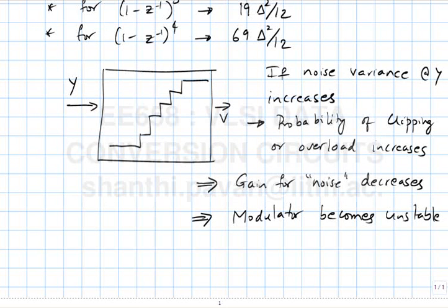Intuitively speaking, we know that the output has to be filtered by a sharp digital filter to get the true representation of the input. And what is filtering? Filtering is nothing but clever averaging, that's all. So the average value of the output bit stream or the output quantization levels is equal to the input. So if the average of some quantity is equal to the input, it must follow that the quantity being averaged must at some times be larger than the input and sometimes be smaller.